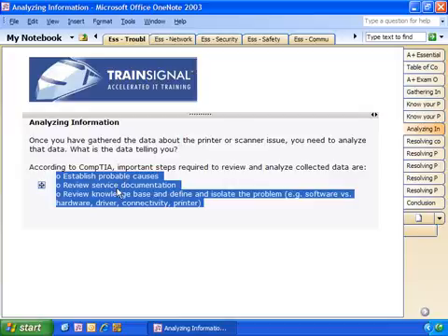Where did the paper flow through the printer? What was the paper path? Where did it come from? Where is that piece of paper going to? Was there something blocking it that caused it to not be able to move on? Review the service documentation. When was the last time that printer had a PM, a periodic maintenance, done on it?